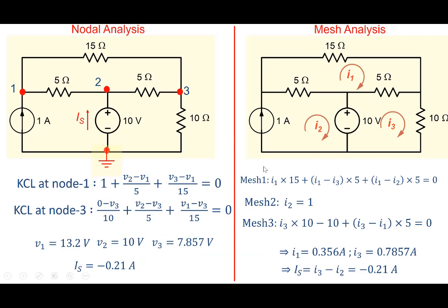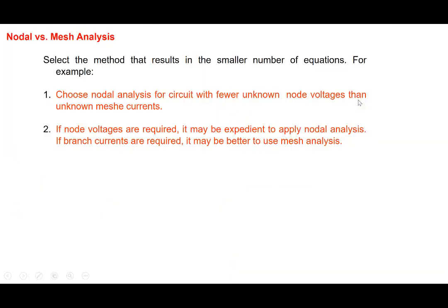Right, so as a summary, we have two very general methods, nodal analysis and mesh analysis. You can apply either one of them to get the answers that you're looking for. In one case, we work with node voltages. In the other case, we work with mesh currents here. And if you solve using mesh analysis, you can get all the node voltages. If you solve using nodal analysis, you can get all the currents that are there here.